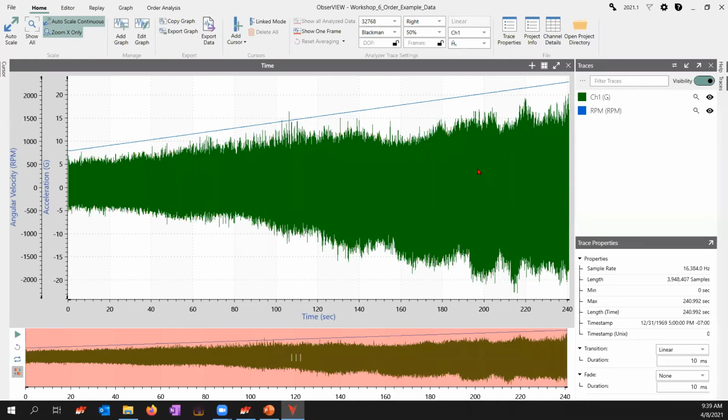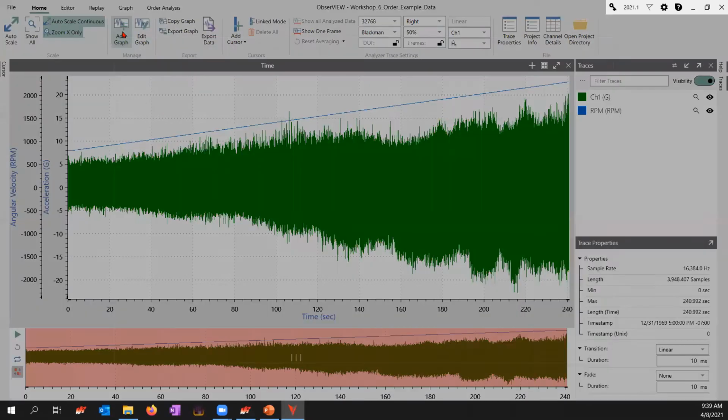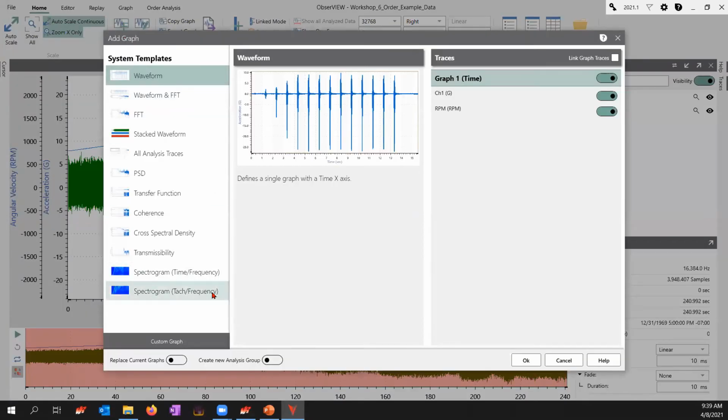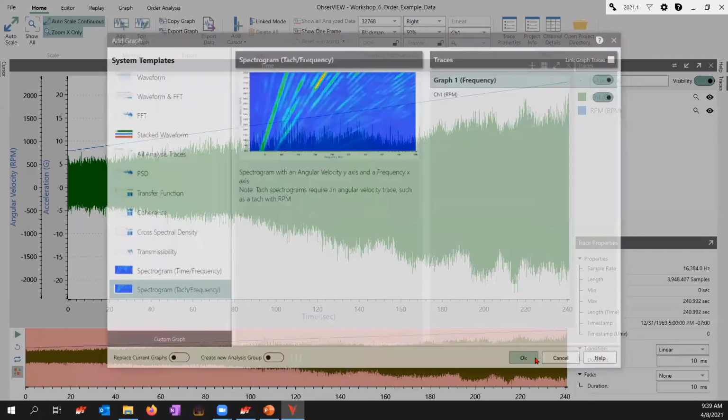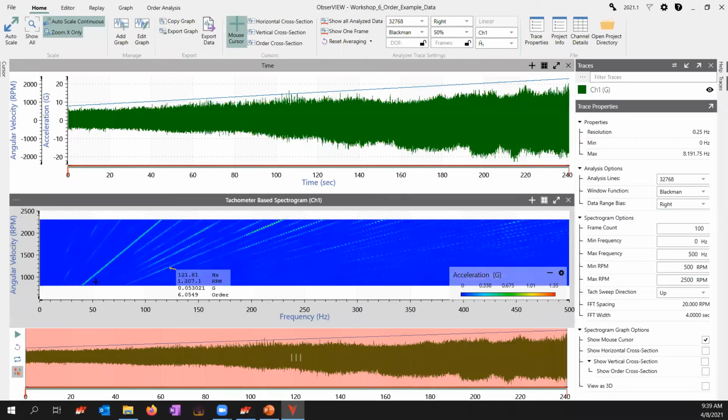So the way we create a sine-on-random test is first we must understand what those frequencies look like. And the way to do that is with a spectrogram. So I create a spectrogram that allows us to look at the RPM over frequency. So let me lower this a little bit so it shows up a little bit clearer. Okay, so now we see these lines, right? Well, what does this mean?